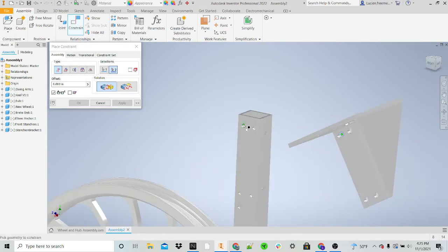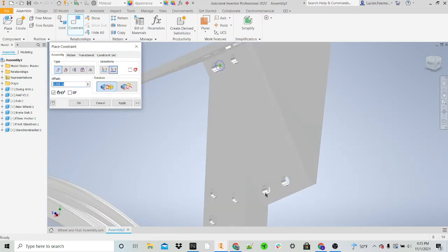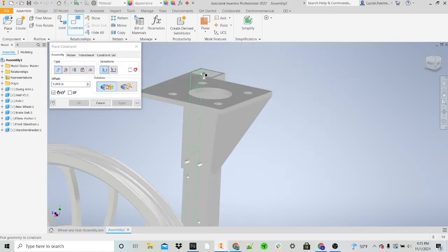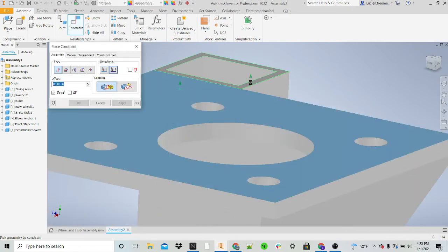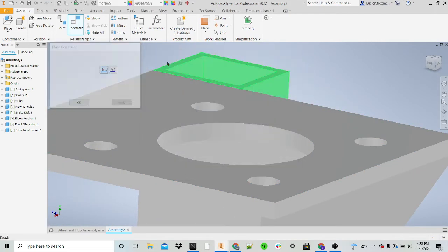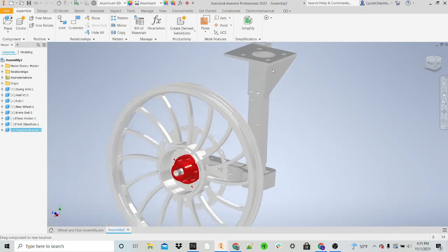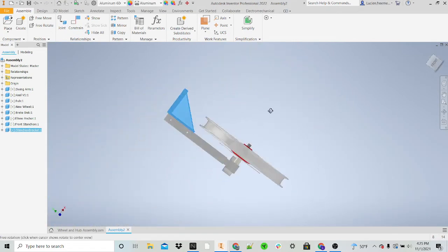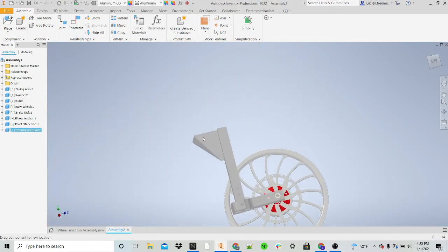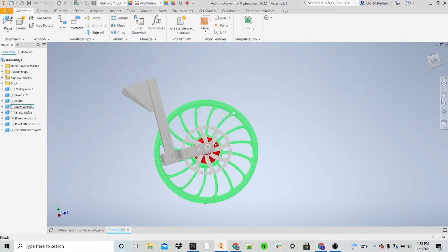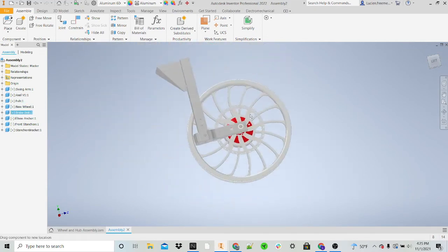Let's put these ones. You got to make sure that you put the right bolt holes together as well. And then we'll take one more right here. Beautiful. And then maybe these top edges just so it doesn't move. Actually, it's already done. Looks like it's just fine. So that's a suspension unit. Easy as that. If I move it around, everything moves together. Nothing goes independent. Everything's constrained.